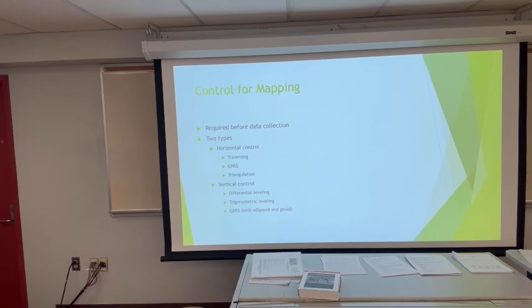Now, back in the 1920s, 1910s maybe, the government started surveying across the country, literally across the country, up, down, east, north, south, east, west. And they did this by triangulating. Essentially, you need a distance on a baseline. You set up on that baseline, you turn an angle to some point.